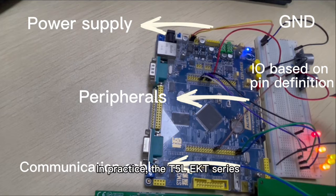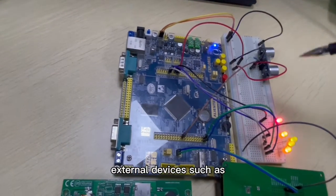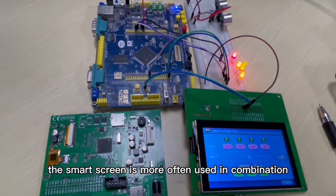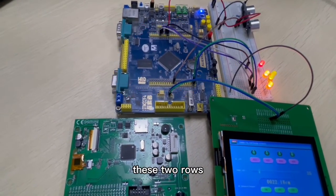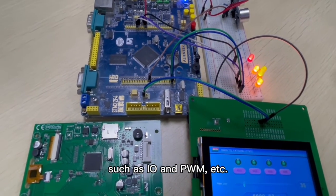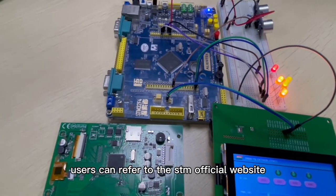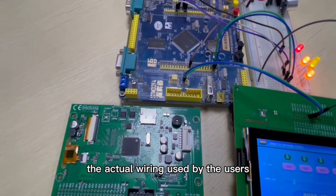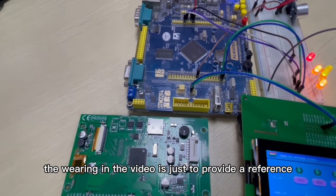In practice, the T5L EKT series products can be directly connected to external devices such as motors via the through-hole pad. However, in general, the smart screen is more often used in combination with the STM32 board. These two rows are the STM hardware interface resources such as I/O and PWM, etc. For a detailed description of this part, users can refer to the STM official website. The actual wiring used by the users should be based on the needs and definitions. The wiring in the video is just to provide a reference.